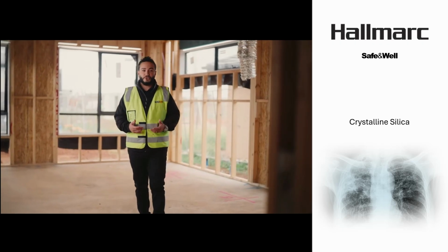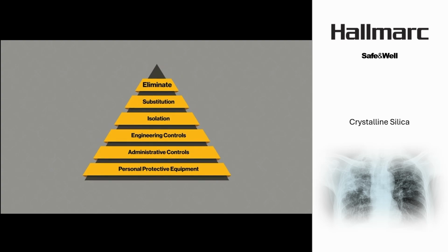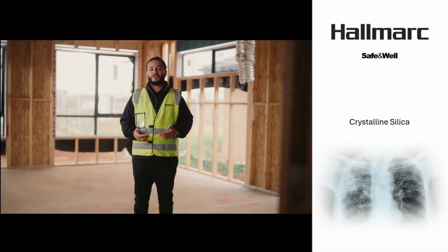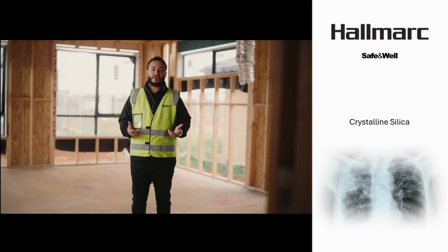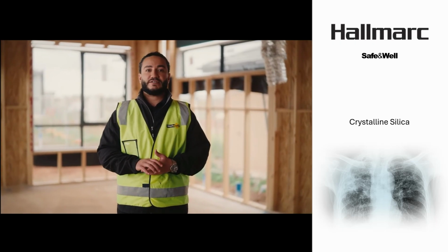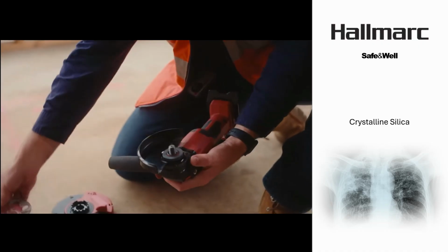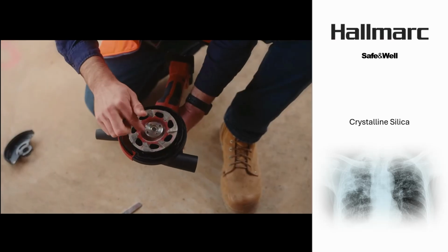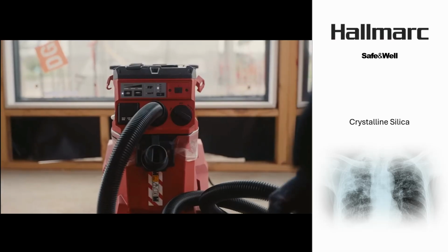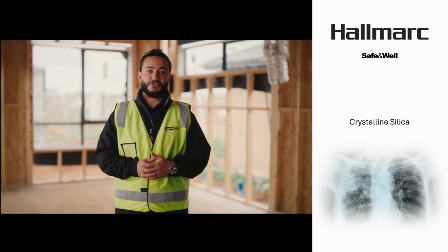When controlling the risks of exposure to respirable crystalline silica, it's important to follow the hierarchy of control. If elimination and substitution are not possible, then engineering controls should be used. The two most common forms of engineering controls are on-tool dust suppression and on-tool dust extraction. Today we're talking about on-tool dust extraction systems. These remove dust at the source when working with crystalline silica materials. An on-tool dust extraction system is made up of a power tool, an on-tool attachment, and a hazardous dust class vacuum. Shadow vacuuming is not an engineering control or a form of on-tool dust extraction.